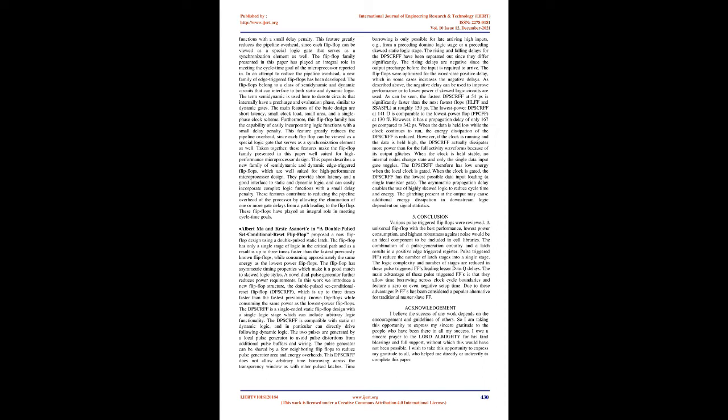Measurement techniques employed in this work, as well as the measurement setup, are discussed in this paper. The interest in high-speed flip-flop design re-emerged recently as frequencies of operation passed 1 GHz. A good flip-flop design affects the power consumed by the clock as well as the available time in ever-shrinking pipelines. The strong driving capability of this flip-flop makes it suitable for GHz design characterized by a short pipeline and high fan-out. The differential input signal nature of the flip-flop makes it compatible with logic utilizing reduced signal swing.